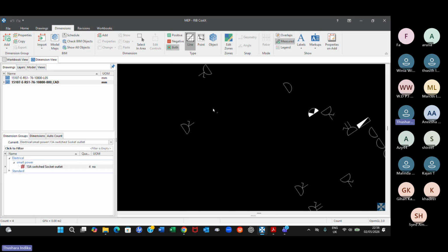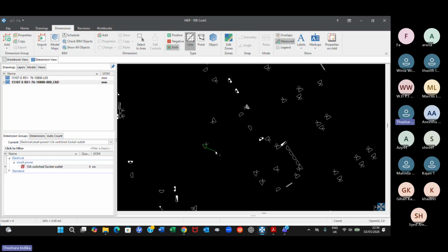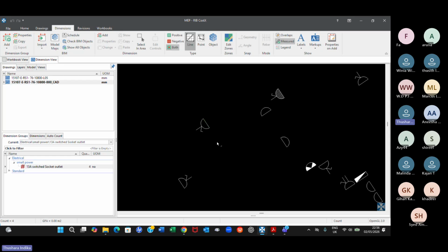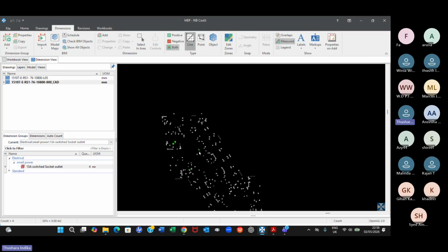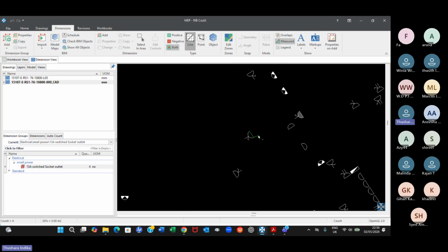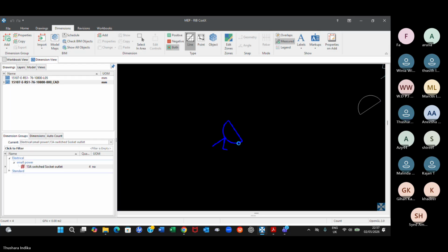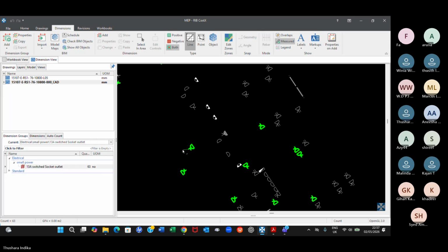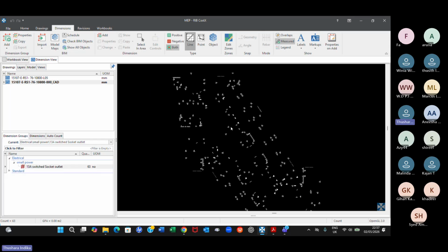But then in that case, there are symbols that have not been selected here. That is not because of a CostX issue. That is the layer issue in the drawing. So now you can see whether you have captured everything. Obviously you have not. In this case, you try with another one also. Again, Control Shift this. Now you can see it became 63.